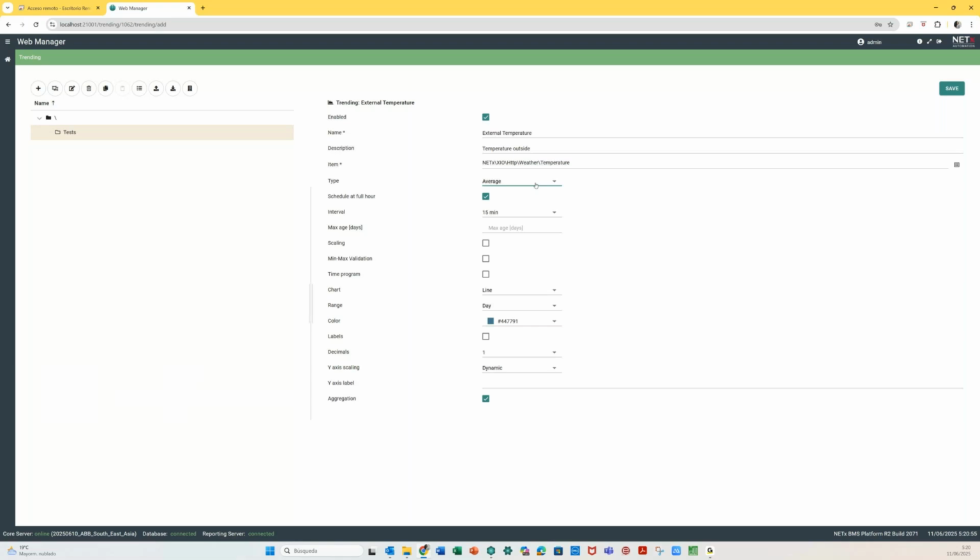So it makes sense to take data every 15 minutes, because if you take data every minute, for example, and the data that is coming is exactly the same all this time, I will historize 15 times the same data. So it makes no sense. So it has to be coordinated with the information that is coming also from KNX.